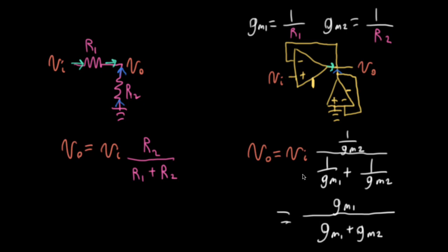In fact, if we wanted to, we could just take this part out altogether, and this would not be a great buffer because obviously there's a current flowing through here. But over here on the right, if we take this out altogether, well, this just looks like a voltage buffer effectively if I'm not connecting anything over on this side.